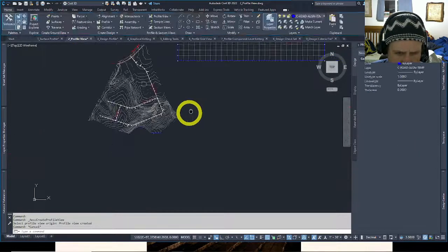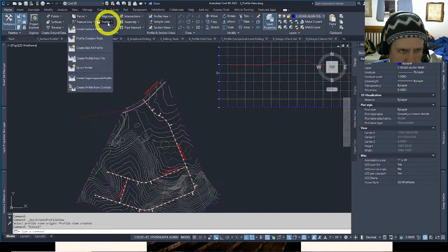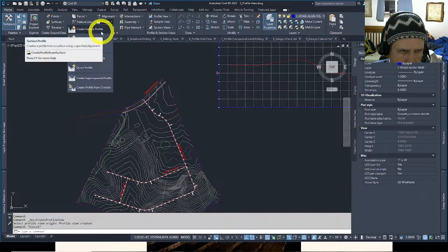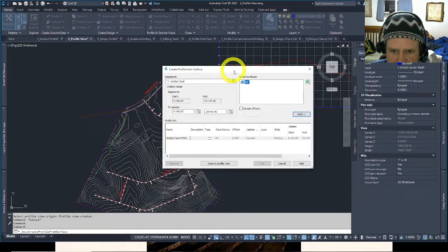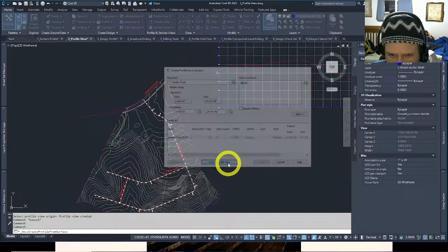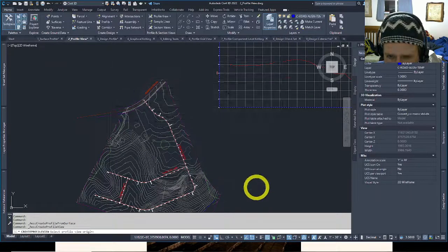There's another way to do that too. We could go this route. We can say, once again, create surface profile. We had already been here. We had already set this up. Instead of leaving this by hitting OK, we can say draw in profile view, and it continues on to this prompt we were just on. We can skip a step.